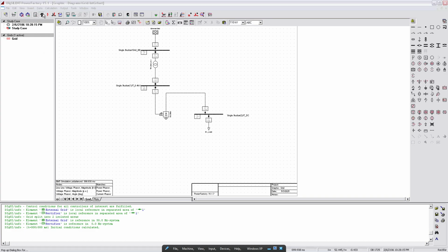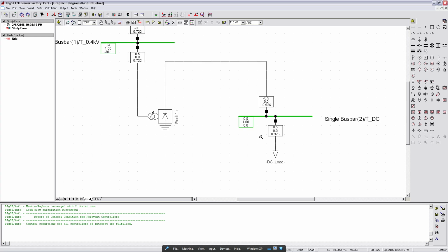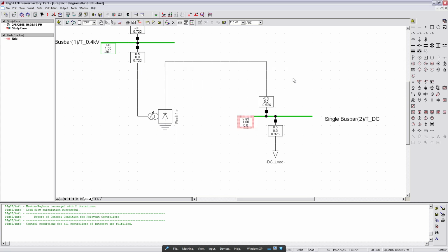Or maybe even a load flow analysis first. So here you see for this, it's 0.5. We don't see the second decimal. So for that, we need to check how we can show until the second decimal point. Edit format for node, and then decimal places. You can select the value. I should get 2. And also for the EU it is the same.